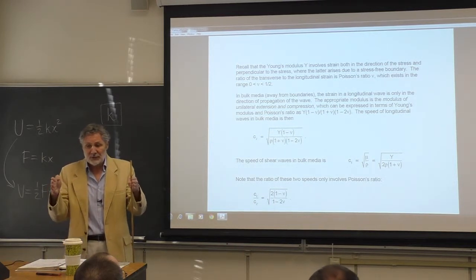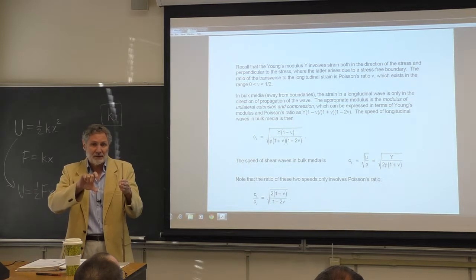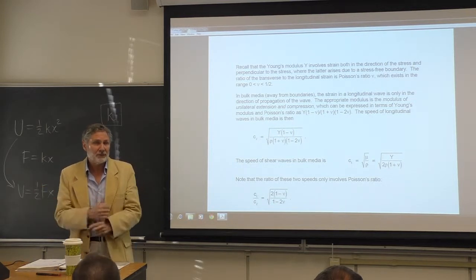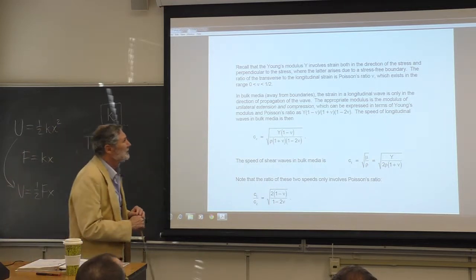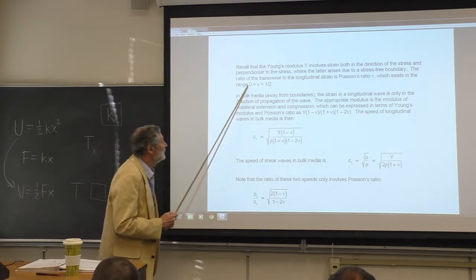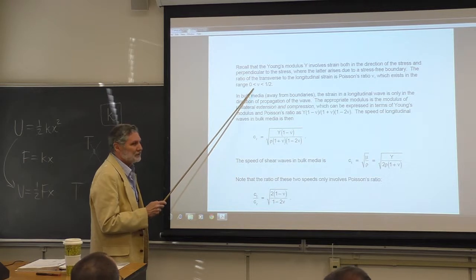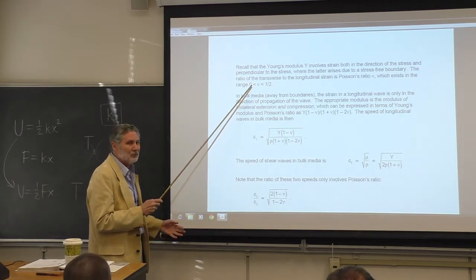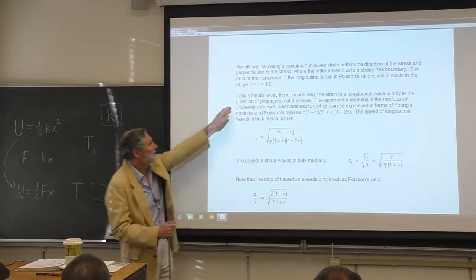So for a certain displacement here, I'm going to get a displacement there. The ratio of that to that, which is dimensionless, is called Poisson's ratio. And it turns out, I keep putting off looking into this, but Poisson's ratio is restricted for classical materials. There's all kinds of weird materials out there now that you've probably heard of, so I wouldn't be surprised if this has been violated.